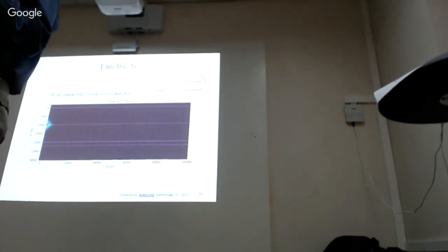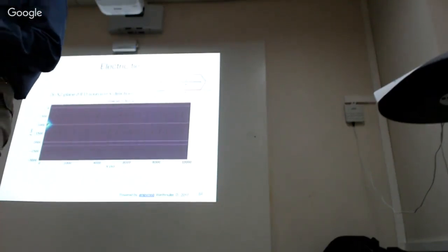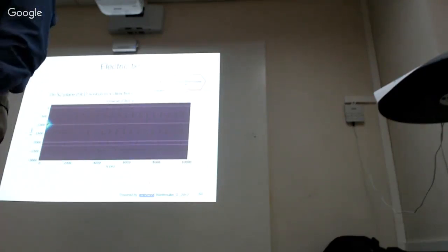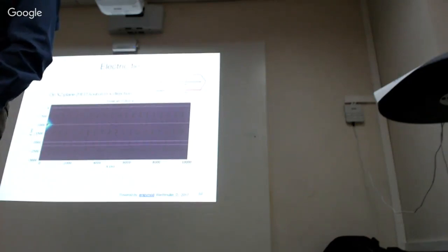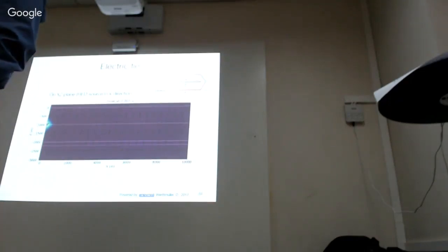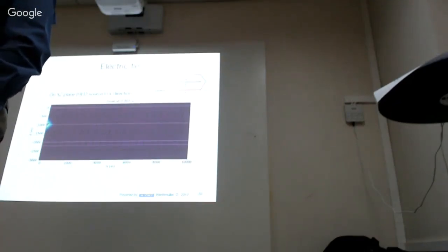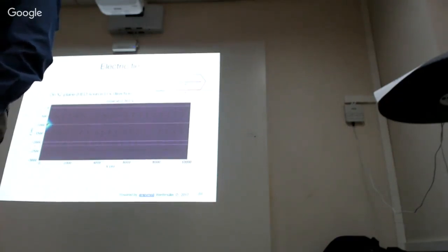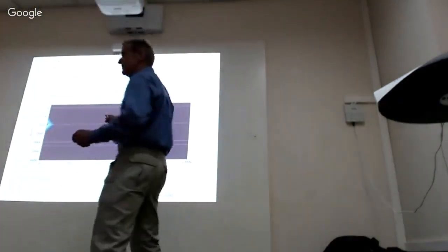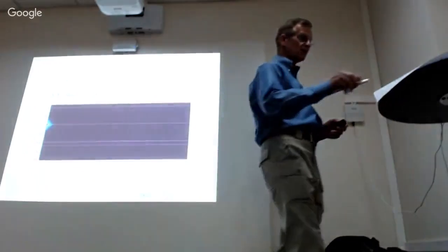Okay, that's fine. But when you look at the frequency domain plots, they're actually pretty hard to make sense of, because you've always got this primary, and you've got this splitting between the in-phase and the quadrature phase. Honestly, you can look at these things and be scratching your head, not really sure what's going on. The intuition for understanding electromagnetics, however, comes from the time domain. That's where this movie is going to be, because it shows time stepping in the time domain, and with that you can see the wave fronts. And once you see the wave fronts, it's like, well, how simple is that? We can also take into account a lot of the fundamentals that we did earlier.